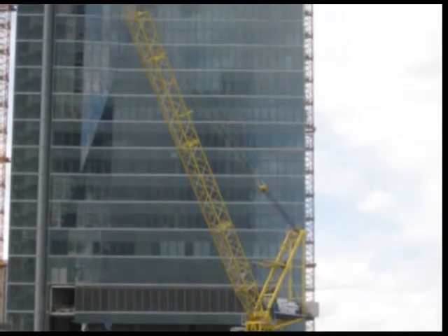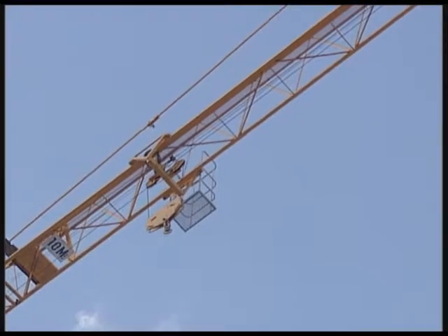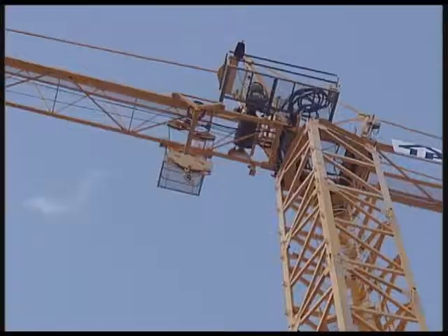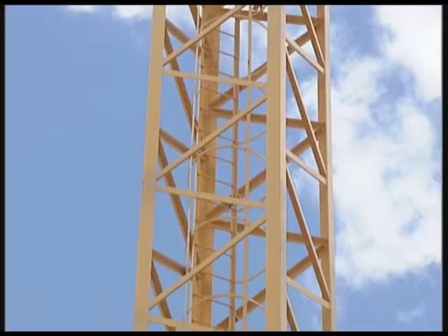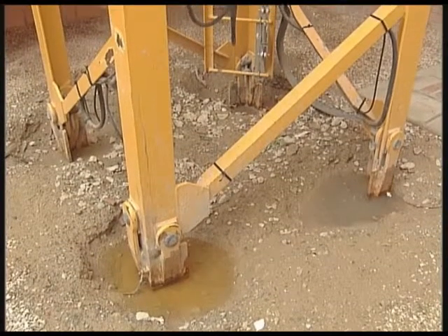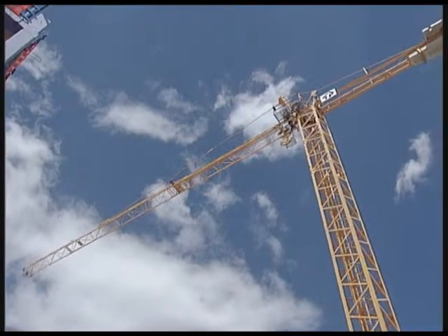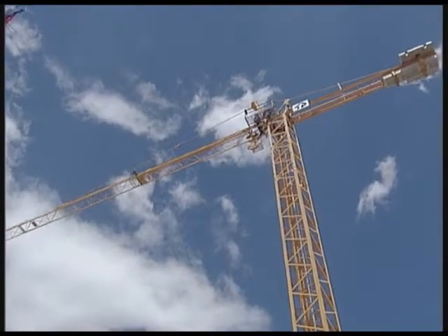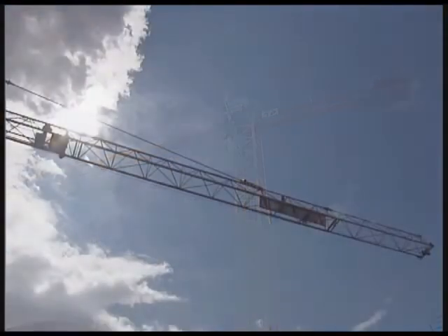These are cranes with a hook that is suspended from the jib or from a trolley that travels along the jib or boom. The jib is mounted on top of a vertical tower. The lower part is joined to the base of the crane. These cranes, that are used at construction sites or for other applications, can be frequently assembled and disassembled, as well as being transported to other sites.